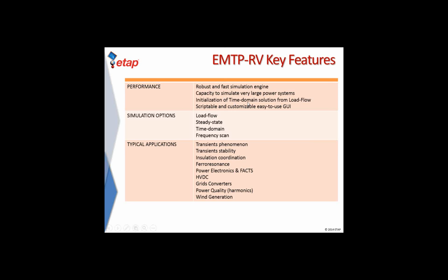Something extremely important in EMTP is that we do have a load flow. Of course, EMTP is not a load flow software like ETAP, but we have a load flow inside EMTP basically to initialize the time domain analysis. When we start an analysis in EMTP, we directly start from the steady state.